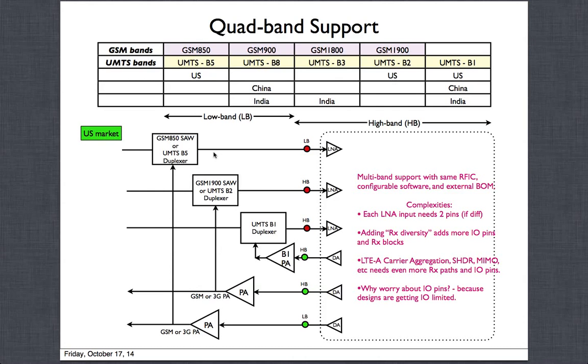The far away blockers could go as high up as 0 dBm, and if you don't have a SAW filter, that will come and hit the LNA directly. So your signal is so weak, say minus 110 dBm, and your blocker is really strong, it will go through some filtering and some matching that you do here, the matching circuitry as we'll talk about. But still, if you can get rid of the SAW, which is a few cents, that's a cost benefit, especially for 2G, because 2G is in the lower end of the spectrum.